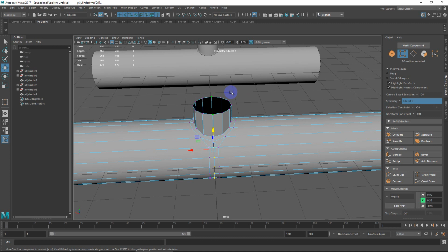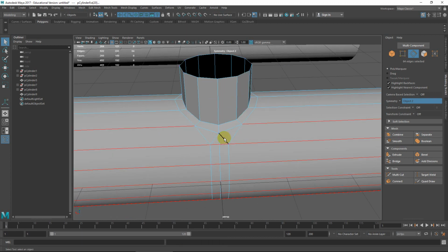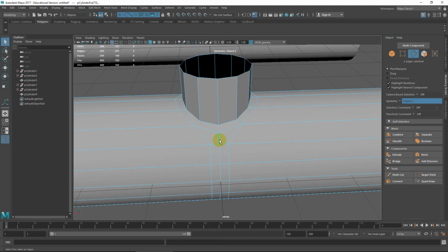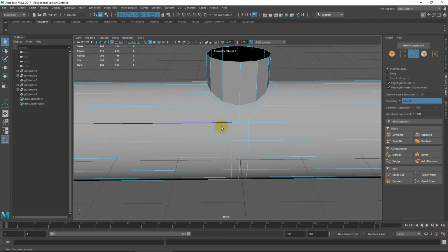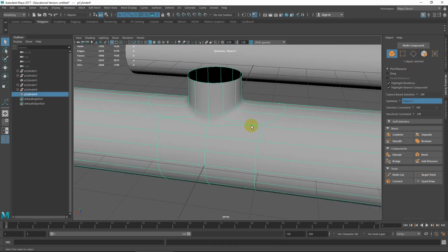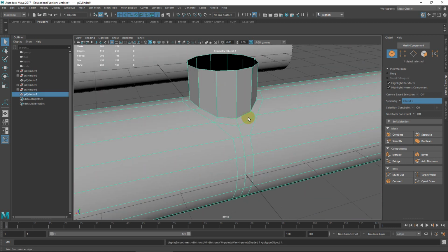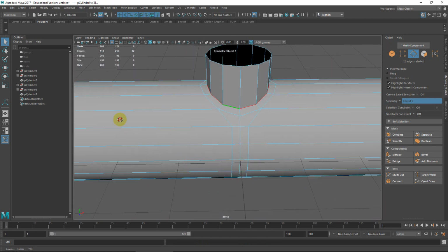I'm going to go to Merge Vertices. So I want to combine the vertices along that center line, so it's going to be back as one complete whole. And then if I go to edge mode, let me just see. I think I'll take out these edges here. So you see what happens is I maintain four-sided polys all the way through, right? Go to object mode. Let's hit 3 to smooth this. This is looking a little better. It's pretty cool, right? If I go to edge mode, I can double-click cleanly across that loop.